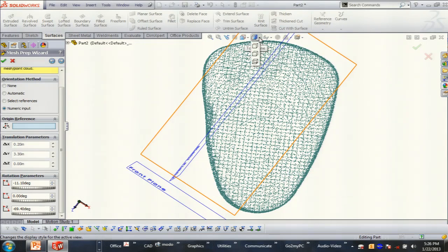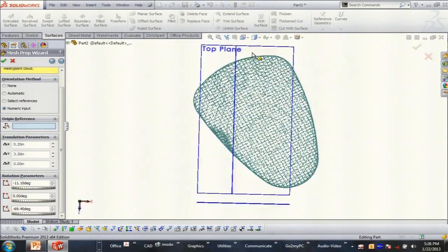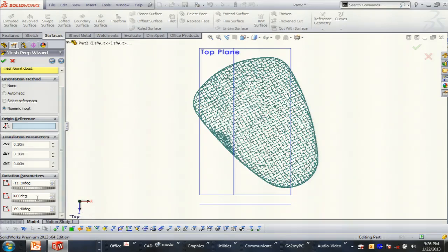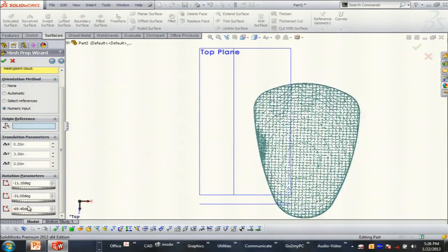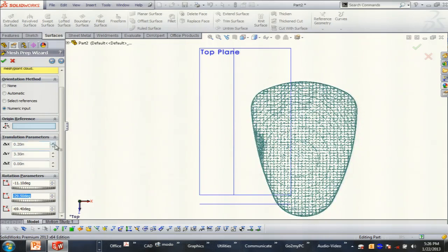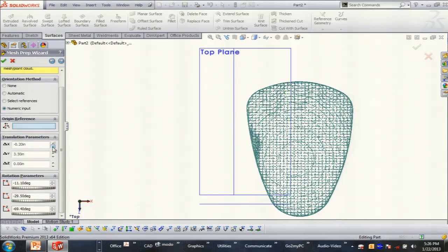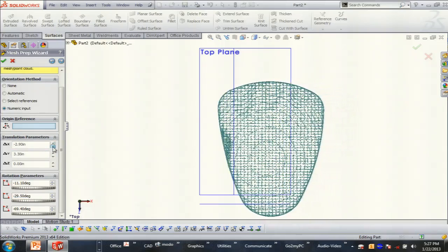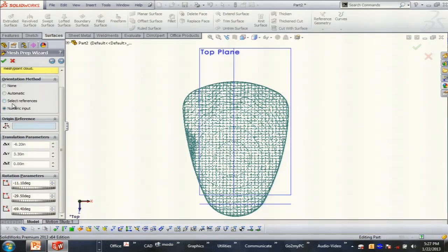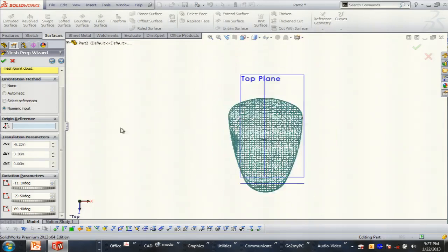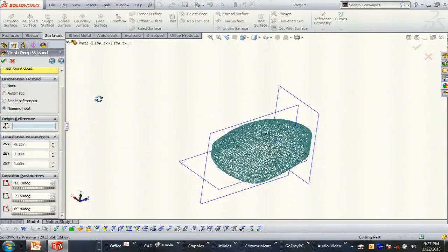So again, going to my top view, off of my y-axis, I can rotate, hold down my Alt key to get finer increments. Okay, I want to move on my x-axis over. And you get the idea, you're just centering it. You also have some other options where you can actually pick mesh points, and it'll reposition to that mesh point. But here I find this most valuable. So at that point, I've got it the way I wanted it aligned in 3D space, okay?